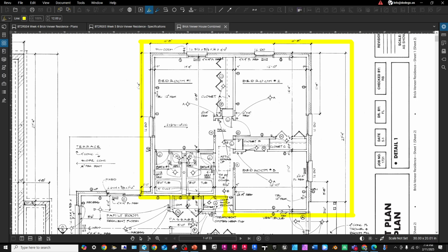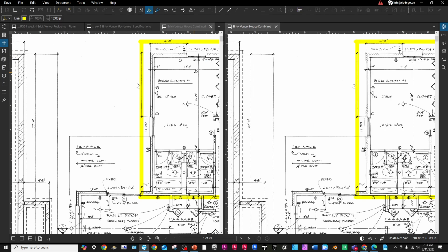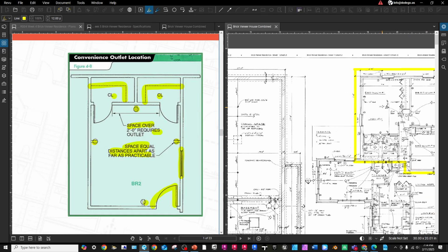Now, this dwelling is going to be sheathed with 1/2-inch rigid foam insulation panels. You're going to have a 1-inch airspace to provide airflow between the frame and that brick veneer wall for ventilation to prevent moisture accumulation within the cavity of the wall. Let's split face it to get a better understanding of what we're saying.